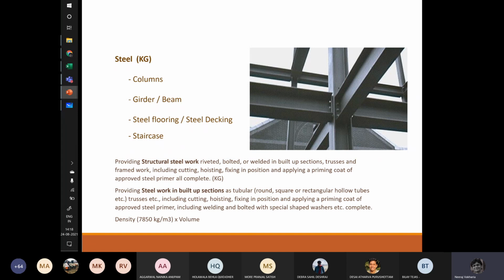And the thing you have to keep in mind is steel is a very costly material. May it be steel or any metal. There are AC pipings which are done in copper. There are GI constructions, GI railing, staircase. All the aluminum ducting, AC ducts which we do, are done in aluminum. So the quantity might be pretty less, but that's why we measure all the metal components in weight, in kg. Okay, so you have to keep that in mind.